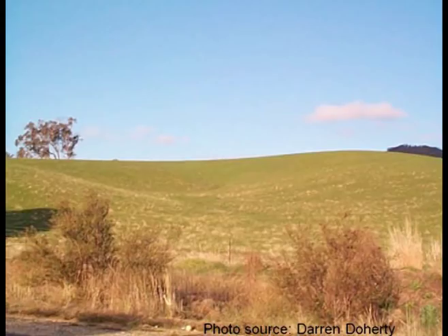When a raindrop hits the soil, it pounds the soil. The finest particles go into suspension in that drop of water, and as that sheet of water moves down slope, those fine particles go with it. When they hit this little flat spot right there, the water sinks in and the finest particles get filtered out. And what are the finest particles, if you guys are doing soils? The finest particles in soils are called clay. Little teeny tiny particles.